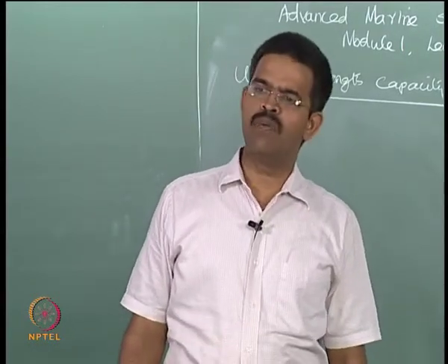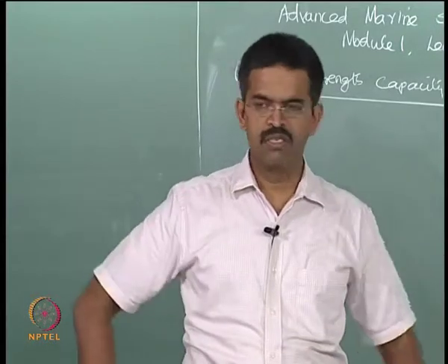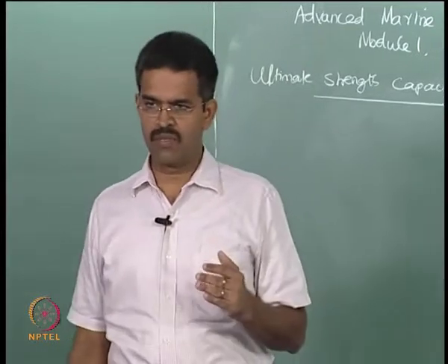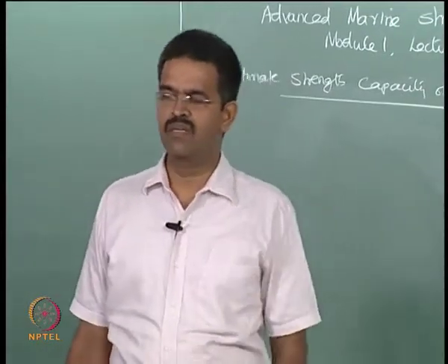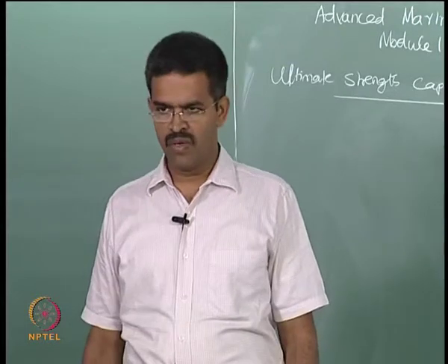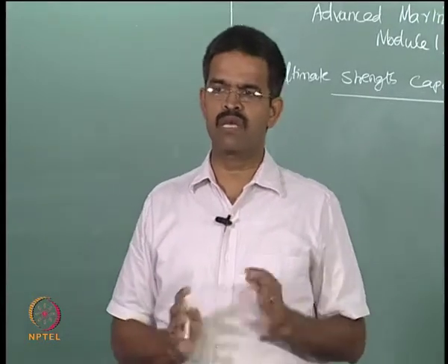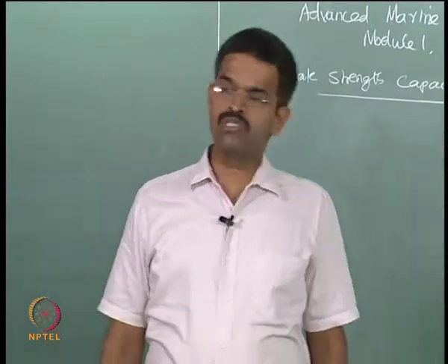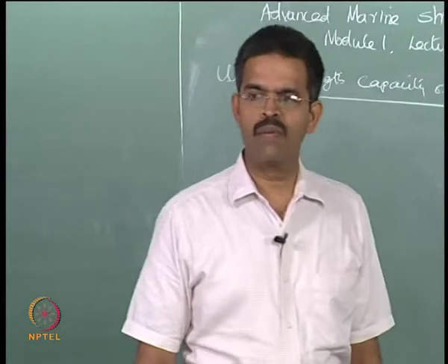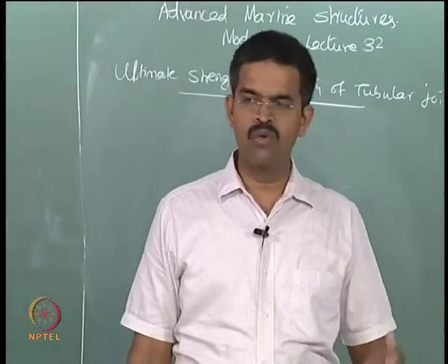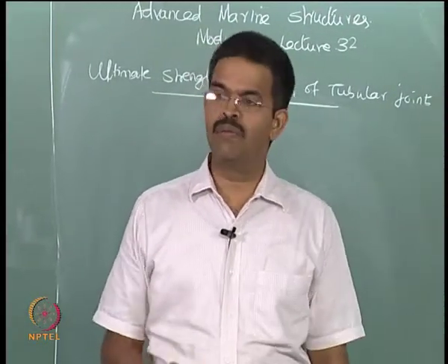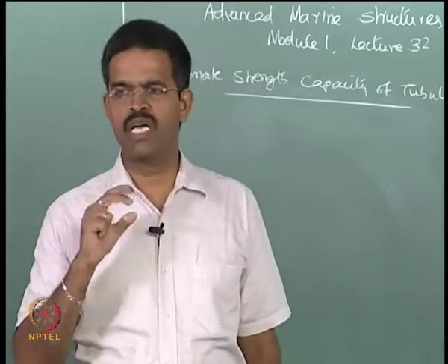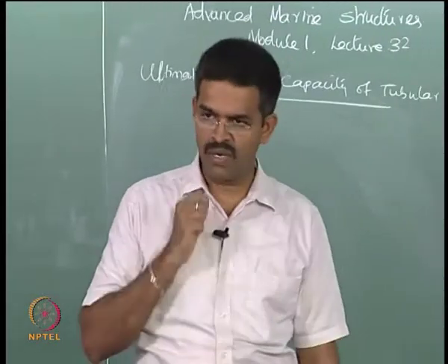So what people have been looking at in past research is, if the brace is subjected to either axial tension or axial compression, what would be the ultimate strength carrying capacity of the joint as a whole. Most of the cases you will see in the literature, these values are always based on experimental results, because analytical modeling is difficult. I will tell you why. There are two important aspects why this kind of mathematical modeling is difficult.